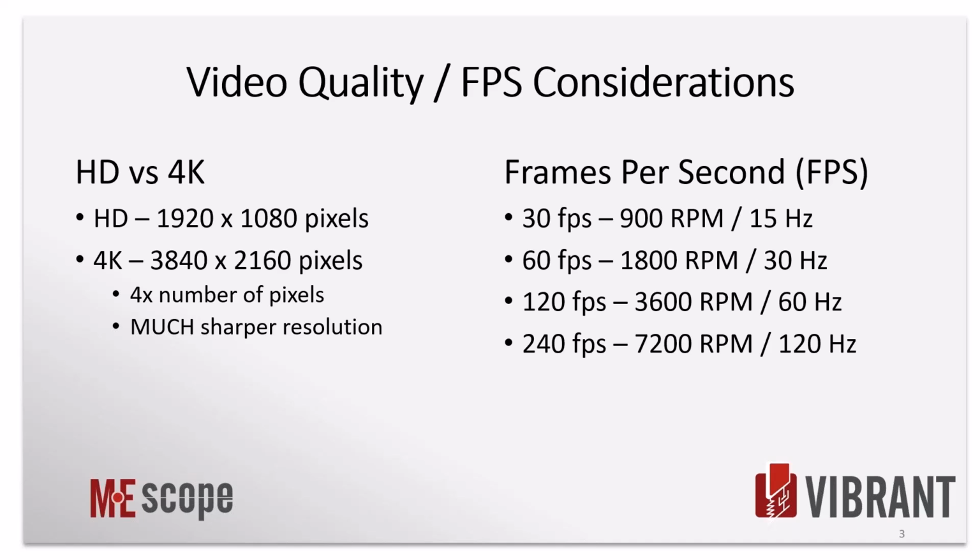But obviously, if you're doing anything rotating, reciprocating, you want to look at multiple orders, or you need to get higher in frequency for whatever you're analyzing, try to determine modes or general ODS or whatever you're going to do, sometimes you need a faster frame rate. And so ultimately, if you're going to do 120 or 240 frames per second, then you're going to need to use HD only, which is not bad, it's still fantastic, but it's just not 4K.